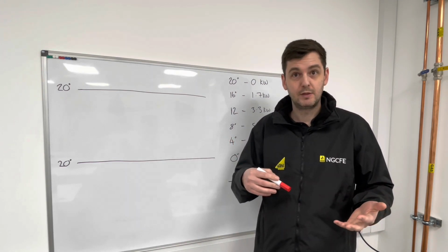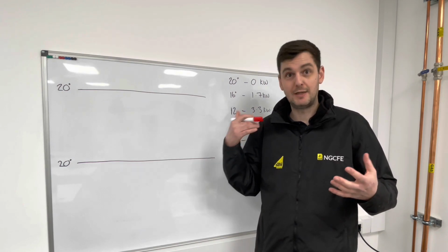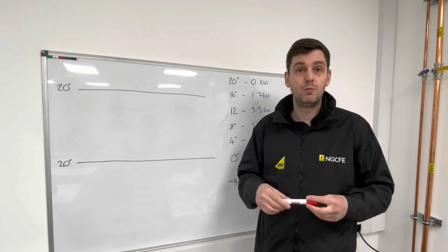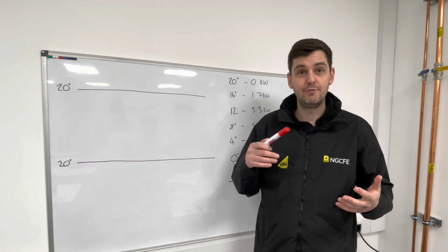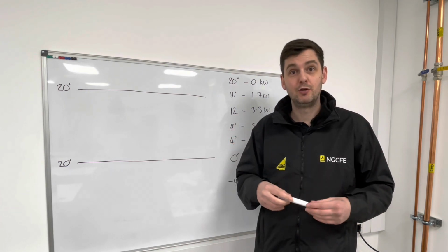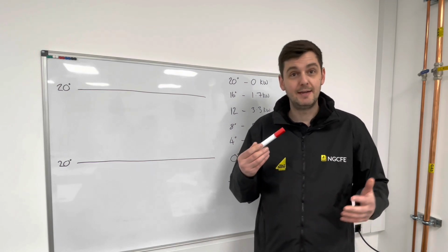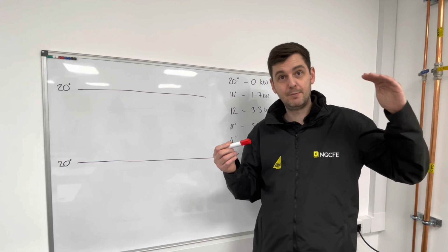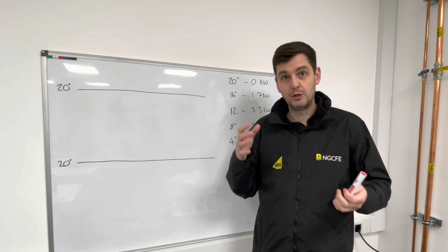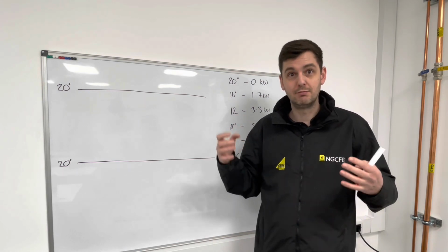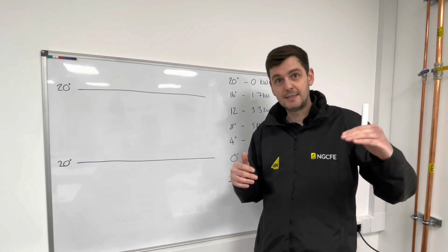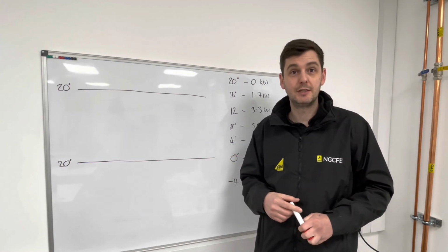The boiler will cut out, but the water that's just left that boiler and the water in the radiators is still hot and is still passing its energy into the room. So what that causes is we very regularly overshoot the room temperature, so it might get to 21, 22 degrees, maybe even worse, depending on the insulation of the property. And then we have the same problem again as the room temperature's coming down. So when the room temperature is coming back down, it will get to 20 degrees and then the heating will come on. But the boiler's then got to work to get the water in the heat exchanger hot and transfer it to the radiators, which has then got to start transferring it to the room again. So then we might get temperatures of 19, 18, even colder again, depending on the insulation levels of the property.